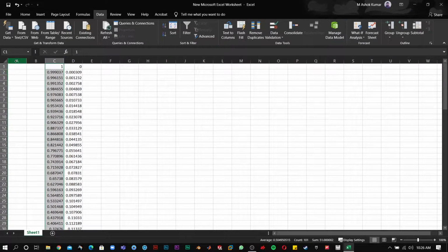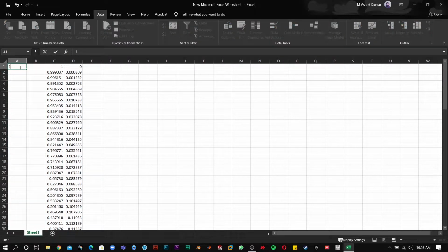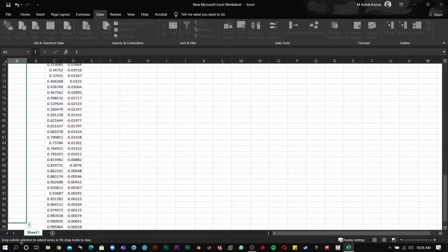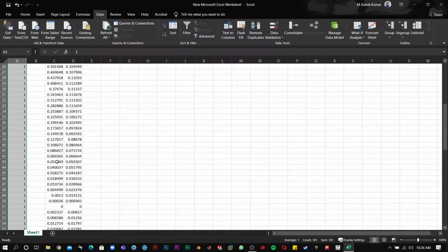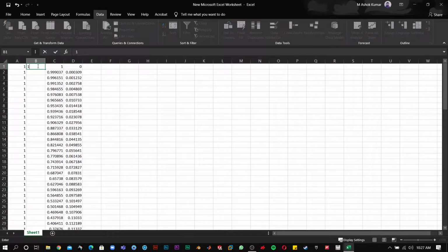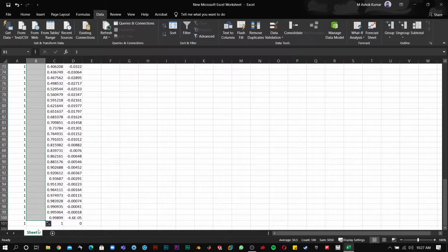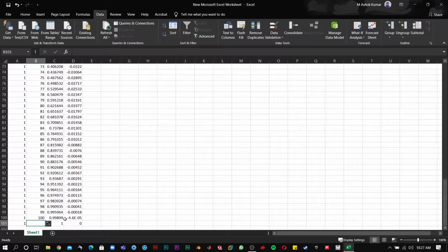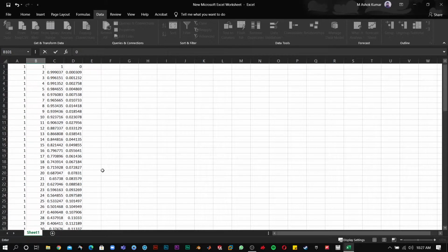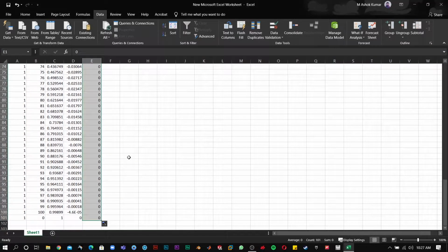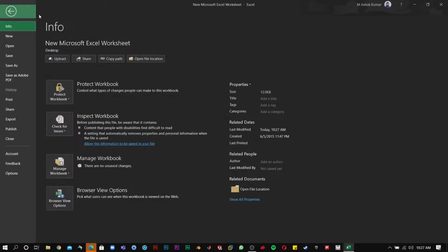So here, the first row will be the group, so it's gonna be one for all. And the next will be the number of points. Let's start with 1, 2, and drag till the last. Make sure the last one is 0 so that it's a closed one. And the last will be the z coordinates. The C and D are x and y respectively. Drag and drop.